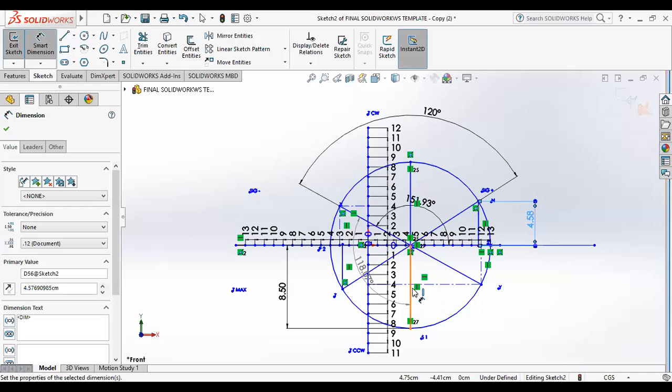Next, in order to measure, there is a plane which is making 60 degrees. In Mohr circle, it will be 120 degrees, always with reference to the x-axis. Since it is minus 120 degrees, I have to rotate it in the clockwise direction. I have rotated it by 120 degrees in clockwise direction. Draw a line from this center. Take the protractor, keep the protractor at the origin C, and measure 120 degrees with respect to point X.